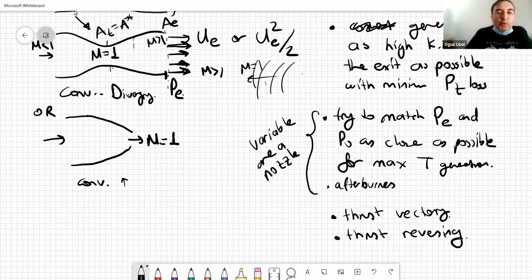Okay. What do I mean by that? I mean, fuel is in liquid phase, hydrogen and oxygen, yes? So they are very cold, actually. To keep them in liquid phase, they are what we call cryogenic. So the fuel tanks of the liquid fuel engines are cryogenic, so they are very cold. And then we basically wrap around the nozzle a lot of piping, spiral piping, and pump liquid fuel around the nozzle, outside, attached to the walls. That cools down the nozzle walls.